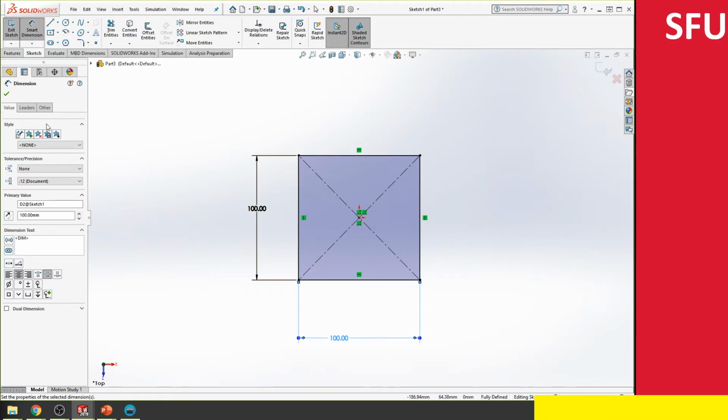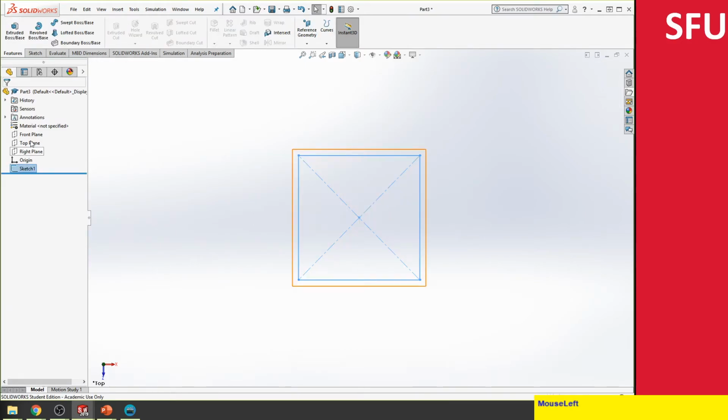Once we have these two, we can create rectangular legs. You can create that in a separate figure. That might actually make it a little bit easier in this case. So again, I click on the top plane, and then I can click on sketch.